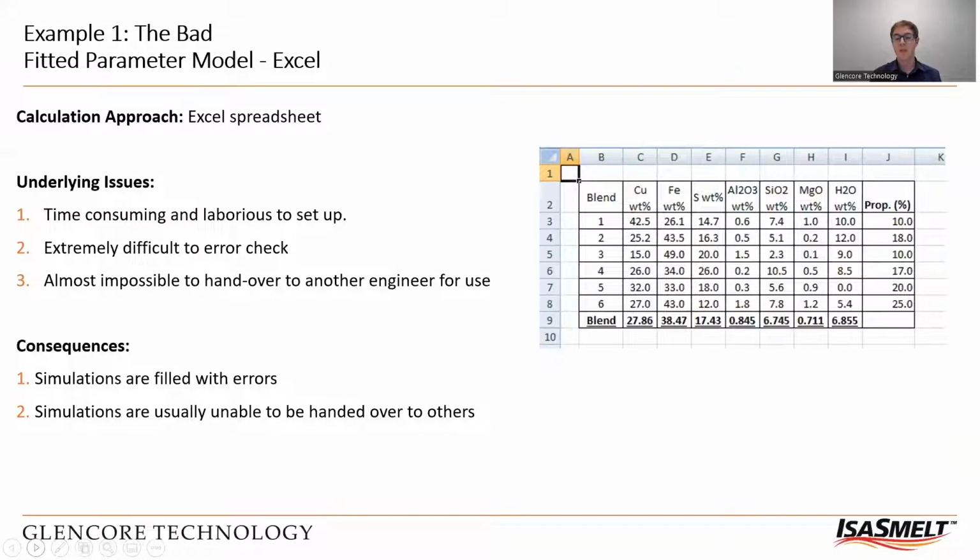So it requires all our pure component data and a lot of relationships between material flows in and out, accumulation equals input minus output. And so we do all these sorts of bits and pieces, and we build up all these formulae. So lots of streams, lots of formulae. We build up in Excel every single little cell. We got a formula there. We also have to input all the thermodynamic information for our pure components, heats of formation, heats of mixing, enthalpy, and functions like that. We have to build it all up, do all our literature reviews, and put all the parameters into our model.